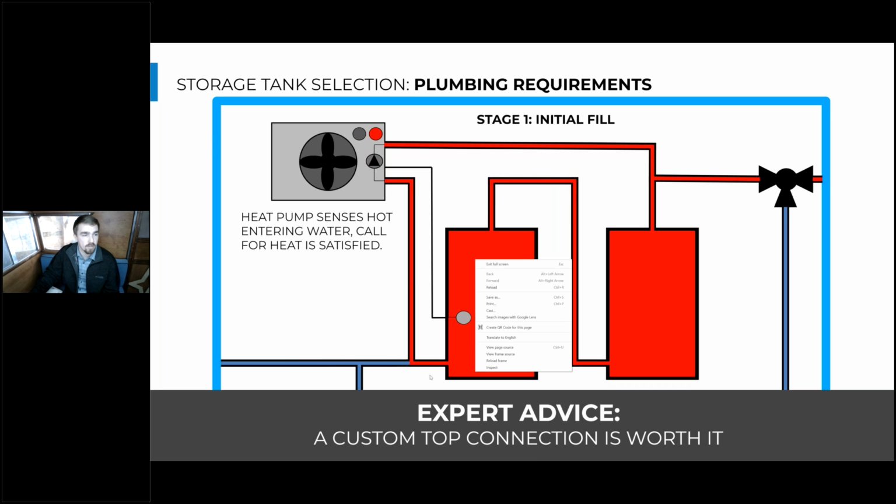And so what happened here is we have stratified storage. So it's charging the tank from the top, and you can picture these two tanks as one tall tank because you have the top of the first tank connected to the bottom of the second tank. So if you were to stack the second tank up on top of the first tank, you would have that hot water charging the top of the tank, then the cold water coming in the bottom of the tank.